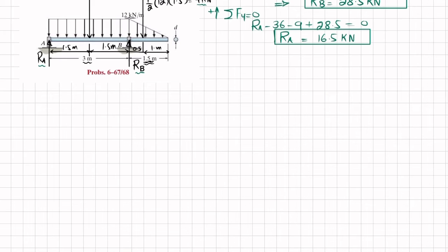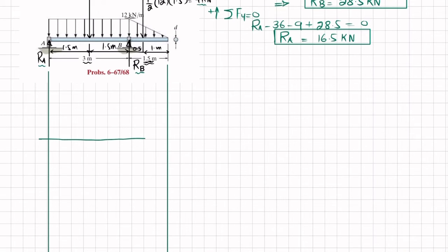For that I have to draw the vertical line from the end of the beam. Clear? And we will draw the shear force and bending moment diagram. Here we will take a horizontal line to show length x in meter. On the y-axis we have shear force in kilonewton. Let each division be 5, so 5, 10, 15, 20 on the positive side, and similarly minus 5, minus 10, minus 15, and minus 20.